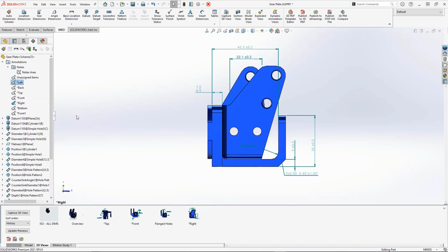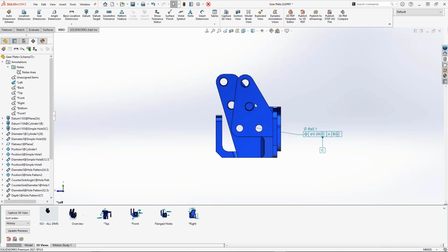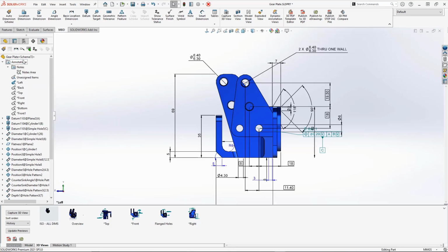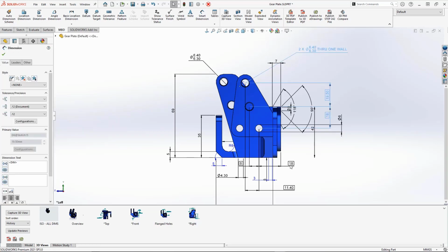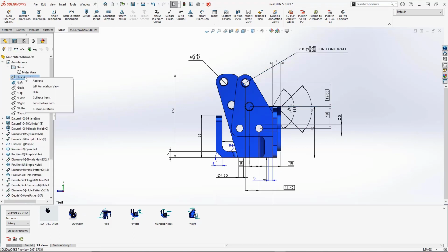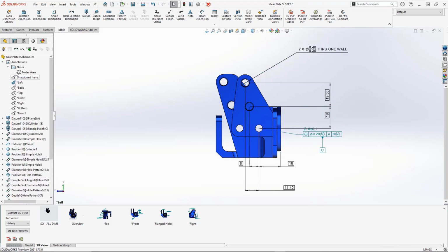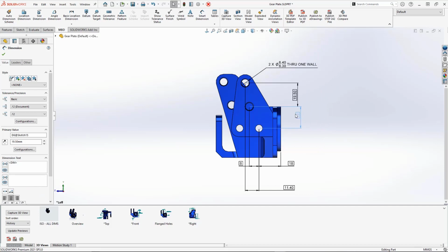We're going to go into the left-hand side. Now, the designer may have already had specific information available through feature dimensions. Feature dimensions are shown in black and sketch dimensions are in blue. These are already included in the model. They may be something that was added or already included through the design process. But we can really at any time move those into an annotation view. What this actually means for us is we're utilizing additional non-DimExpert information to create and document these 3D views.